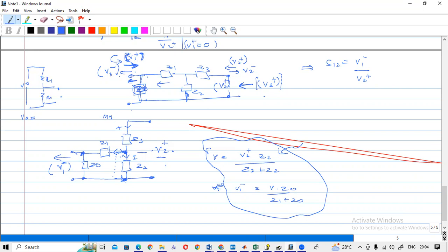Let's say that this is R1, R2, R1 plus R2 times I. Then you are applying Ohm's law here. So let's say that the voltage is V. So V is equal to R2 times I. So you are going to divide this, then I cancels. That means this I should be coming here. If this has a load, you can't put the voltage dividing rule at once.